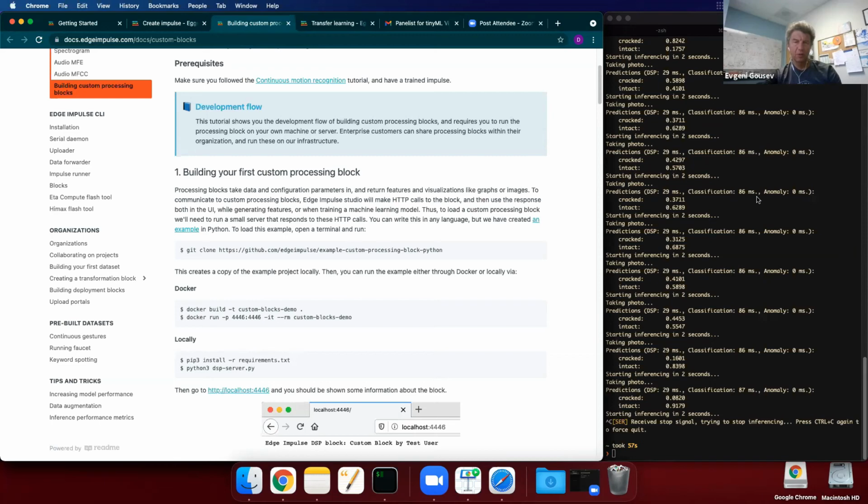A couple more questions. There is a question from Dima. Is it possible to use an alternative camera module with Himax WE-I Plus? The one you showed today is the VGA monochrome, and he would like something more like 2 megapixel RGB, for example, OV5642. I'm not completely sure if you would be able to get 2 megapixels with RGB. I do know that the camera interface on the WE-I can support other cameras, but I would have to get back to you on if it would support that exact use case.